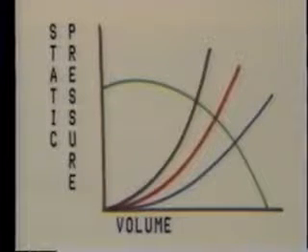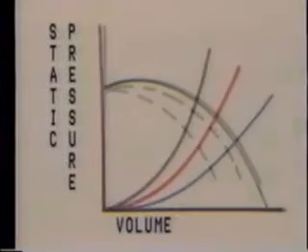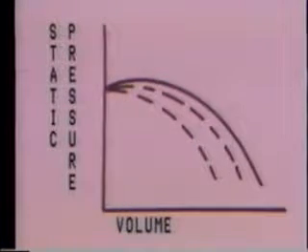As the terminal unit dampers throttle, the characteristic curve, the resistance curve, shifts. The pressure senses this shift, and thereby the inlet vanes are throttled accordingly, shifting the fan curve, and in turn establishing a new operating point. The new operating point of fan operation will depend upon where the terminal units being throttled are located in the system. Fan discharge pressure will not remain constant since the location of the pressure transmitter is at the end of the system.